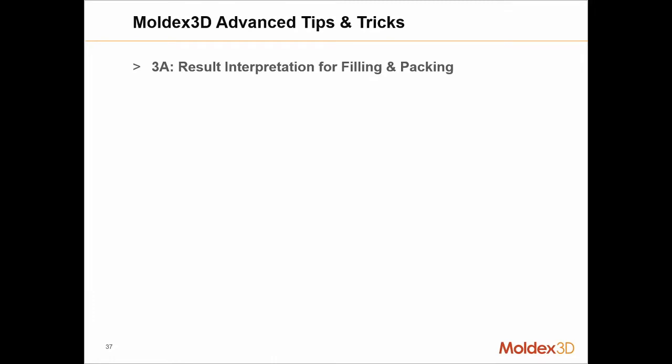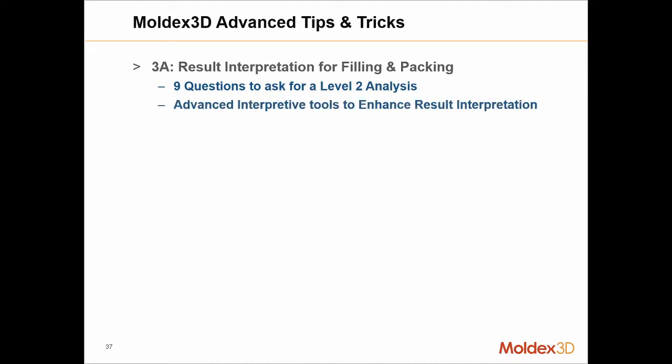My name is Alex Baker, and we're going to be going over result interpretation for the filling and packing stages, the first of two result interpretation sections. In this section, we're going to go over the 9 questions that you need to ask yourself for a level 2 or a filling and packing analysis. We're going to interpret the results using some advanced interpretive tools, and then we're going to make informed decisions based on the simulation results.